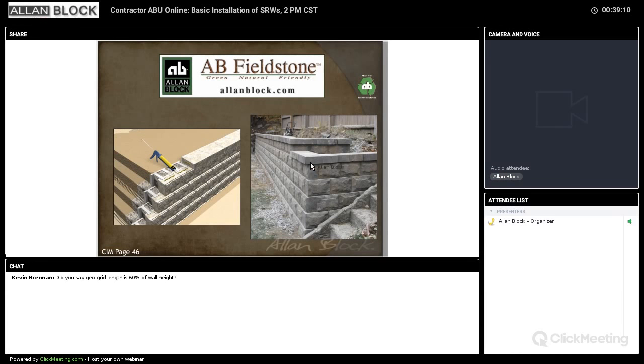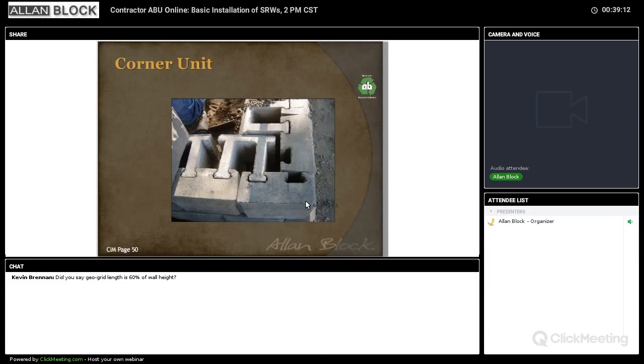And so let's take a quick look at the outside corner. An outside corner, every 4th block that's made has a finished end that can be used as a corner. So you can have the anchoring unit go between the last block, the corner block, and the next block to hold the block together. And then you're going to put a single unit in so you get back on running bond. Because typically we want to have the anchoring unit with 1 face unit, or 2 for the long face units.